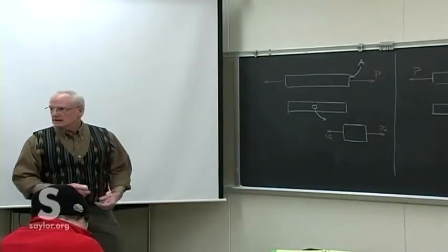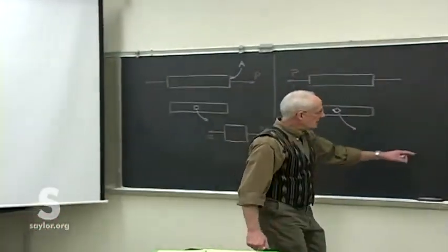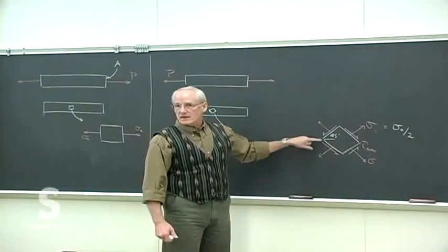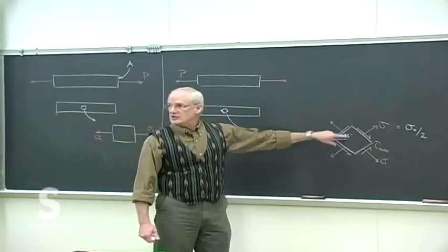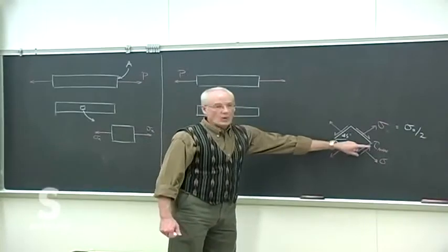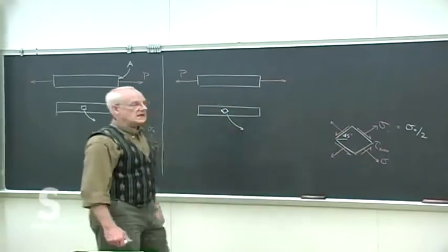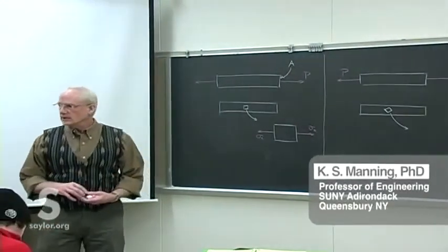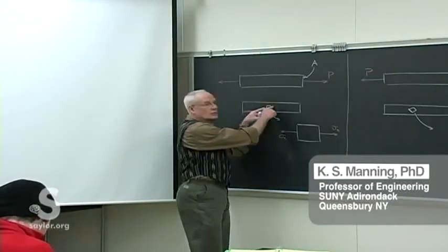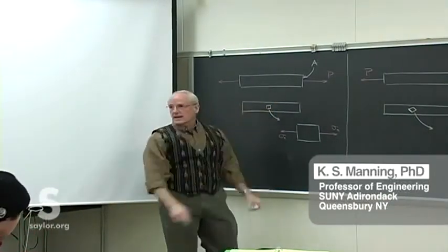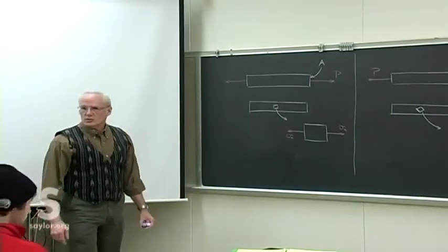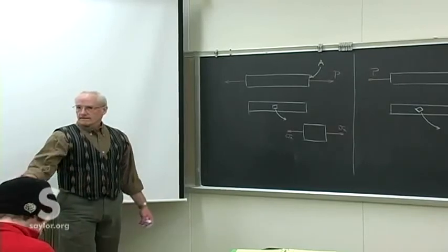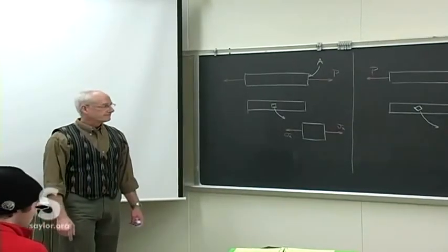Any questions? As we go through these things, remember that the shear stresses must be oriented in relation to each other in this way. They might be in opposite directions, but if one's in an opposite direction, they all are. And no matter what the angle, all four of those are the same magnitude, or we don't have a static equilibrium on an element, which we must for any element, any parts, any total structure that we might look at. Questions? Phil, questions? Good.